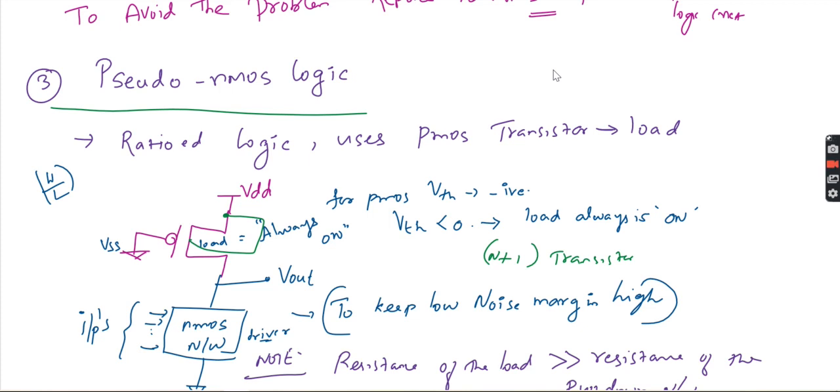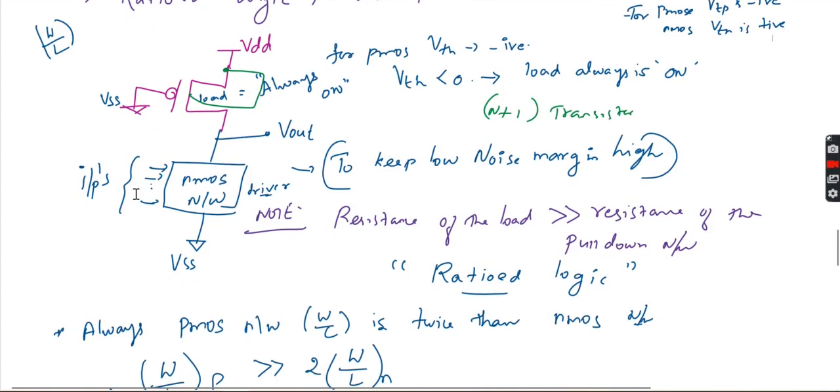When will this transistor be turned on? This is VSS, right? For PMOS, as you know, the threshold voltage is negative; that we already know. For PMOS, VTP is negative. For NMOS, VTN is positive. Now the NMOS network will implement the circuitry here.